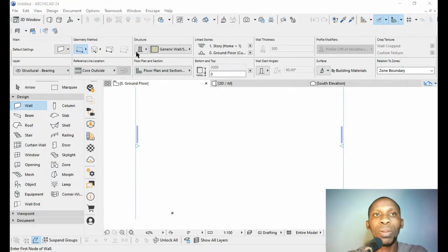Now here we have three different wall types. So this is complex profile walls. We will talk about complex profile later on in this training. When you have made a design or a shape on complex profile, you can click on this complex profile here and come to custom, and you see the complex profile you did on this particular tool here. But now we are not making use of the complex profile because we have not done any. It's not a facial or a thin wall or something like that that you want to project out, even a concrete facial also, right? You can actually do that on the complex profile.